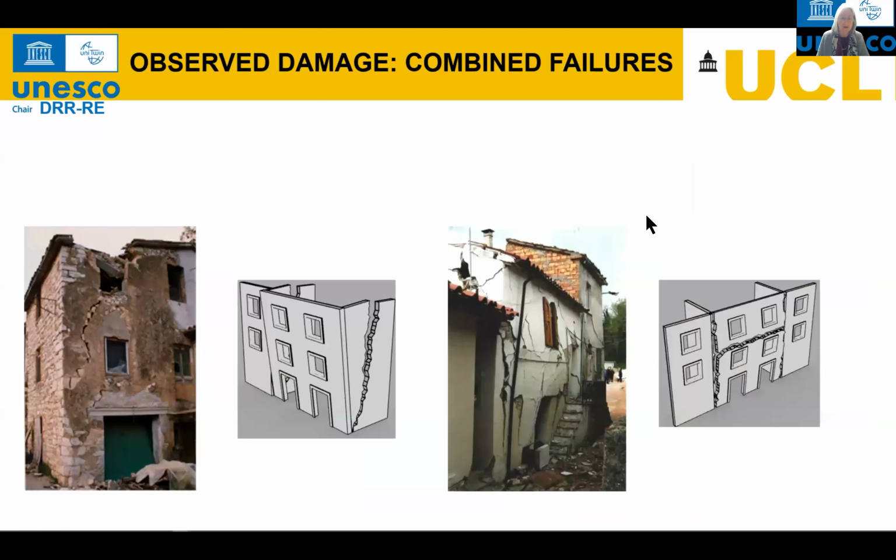When the structures are better connected at the top of the walls, when the facades are better connected, we can see that they actually fail in a different way again. And here we can see that this facade, which was well connected to the back and to the roof, so much so that the roof failed mid-span here, is bringing with it in its out-of-plane behavior also part of the side walls, also part of the in-plane walls. And therefore, we can represent it with this type of sketch.